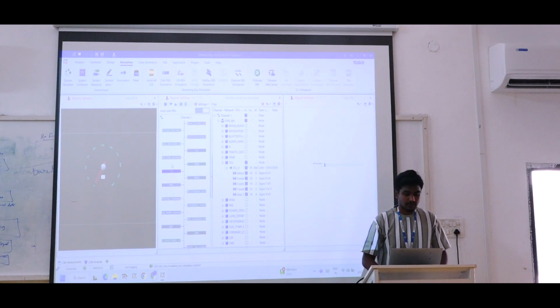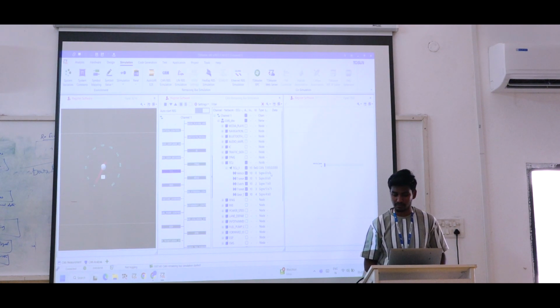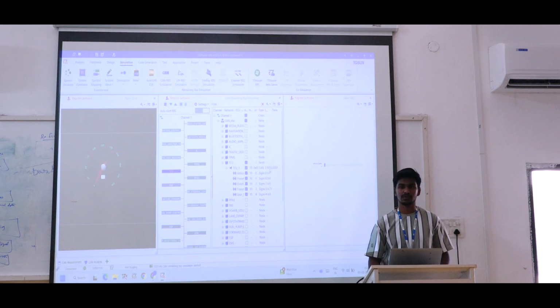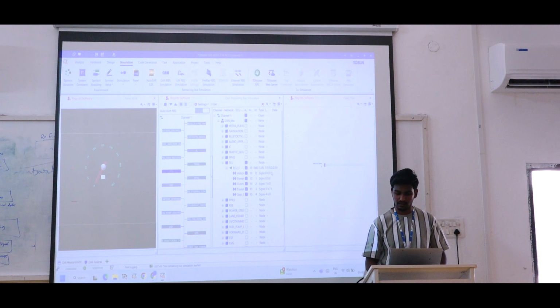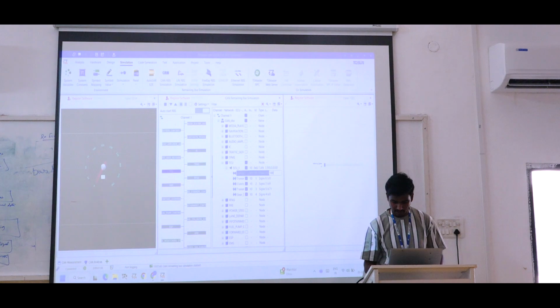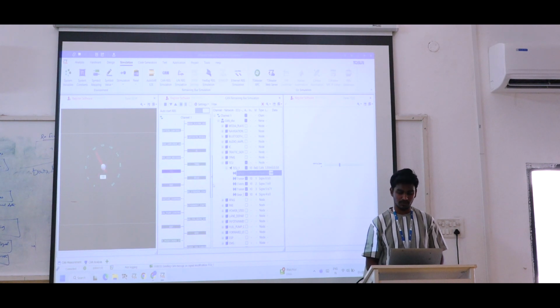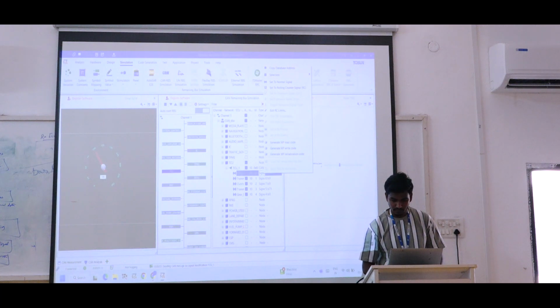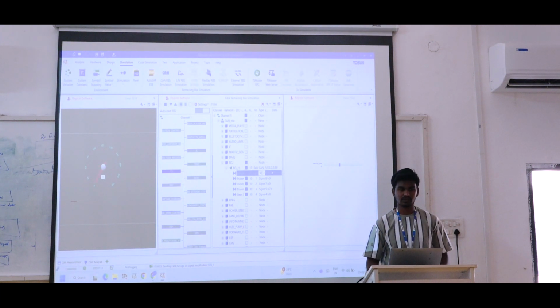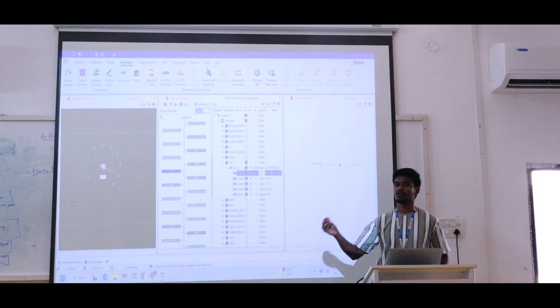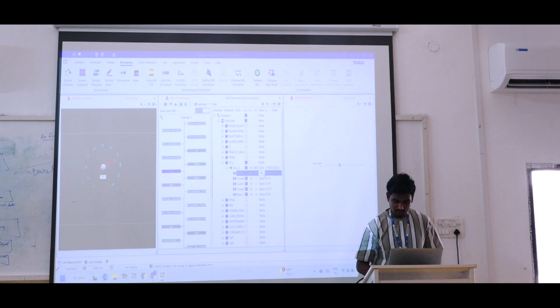So as of now, in our CAN test bus simulation, that means CAN RBS, we are able to transmit some values by the manual values, which means normal signal. So now choose normal signal. Here we can generate some values like, for example, 100. We can mention the value here. One more option is that we can set a rolling counter. Some of the values run automatically based on the rolling counter limit values. So now we can change this again to normal signal.